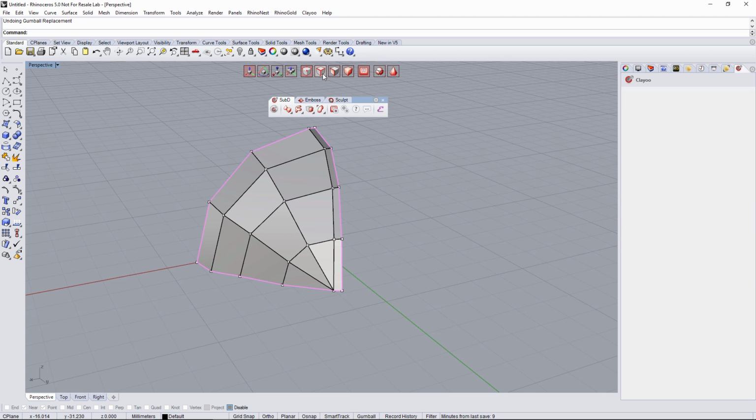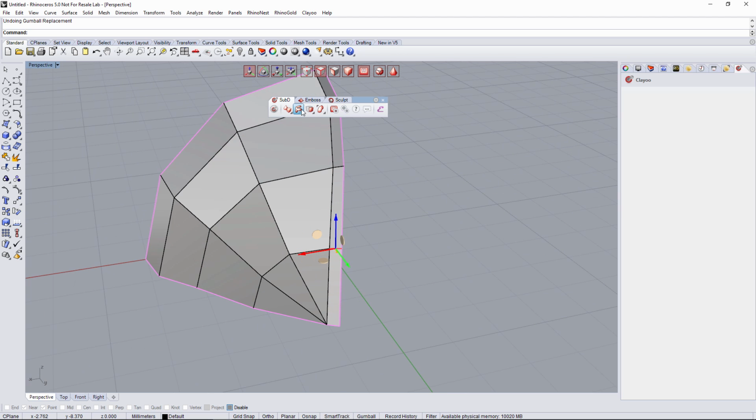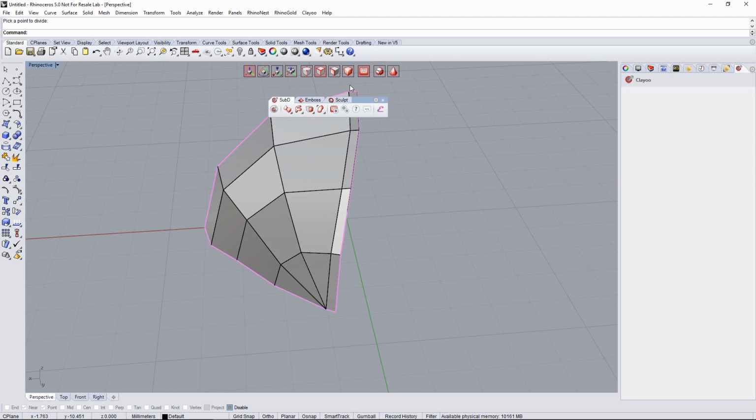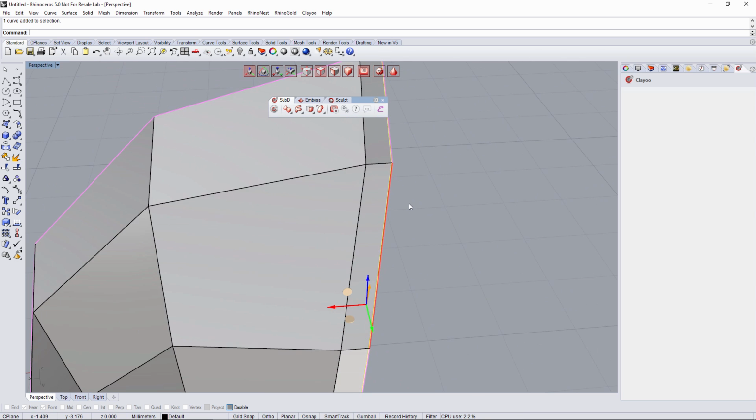Okay. So what I'm gonna do is I'm gonna extract a curve from here. So how do I extract the curve? I'm gonna select first of all the edge that is perpendicular. One of these edges is gonna be fine, and then run in the creation tab the command extract isocurve. So extract isocurve, and I'm gonna extract this isocurve. Doesn't matter if it's perfectly on the edge or more or less on the edge. Okay. So in here I have the curve that I've extracted.